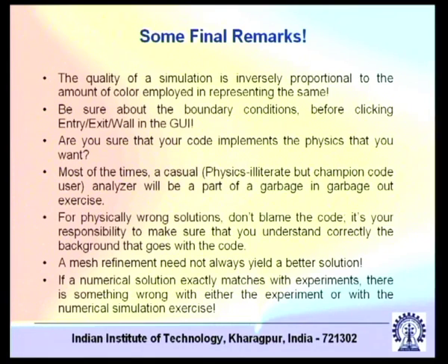This is very tempting, because what we see very commonly is that you click, for example, the outflow boundary condition where it is not exactly outflow. Let us give an example. Let us say you have a thermally fully developed flow along x. Then it is not del T del x equal to 0 at the outlet, but del theta del x equal to 0, where theta is (T minus T wall) by (T bulk mean minus T wall). If you are solving for temperature, you will most commonly be tempted to click the outflow boundary condition because it is available in the GUI, but that will be totally wrong if you are implementing a thermally fully developed flow. You have to somehow implement del theta del x equal to 0.